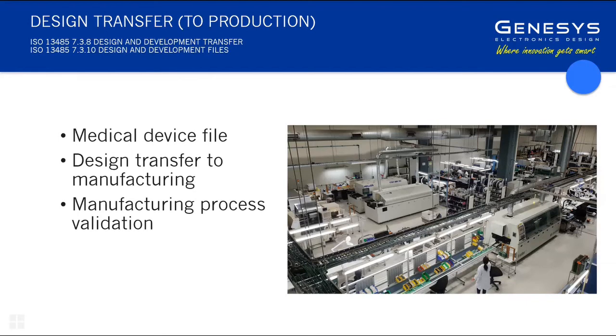This is actually validating that the manufacturing process does what it's supposed to do, and the design transfer, which is the engineering documents going into the manufacturing environment, are effective in allowing the manufacturer to make the device, use the appropriate components, make sure that the assembly process is reliable, make sure that the end-of-line production test process gives adequate test coverage so that every unit off the line is fully functional and capable, etc., etc.